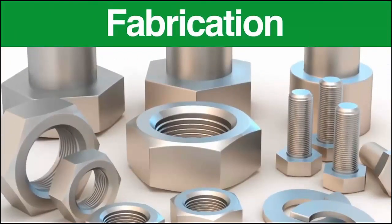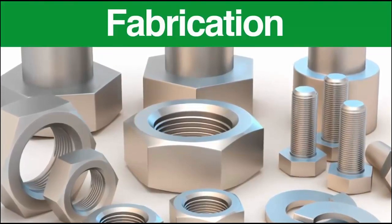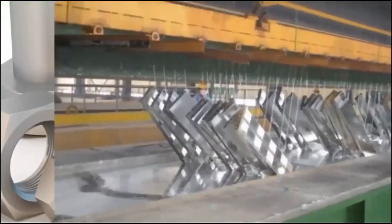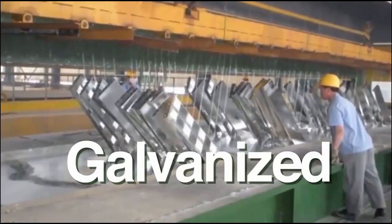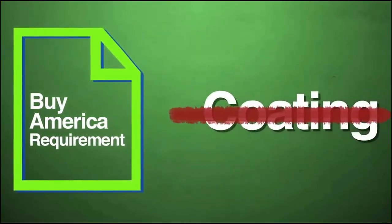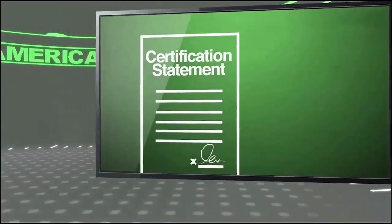Bolts, nuts, and washers used as connectors require separate certification statements since these are produced at different locations and use different manufacturing methods than the structural elements. The location of the final step, where a product was coated with paint or galvanized, must also conform to the Buy America provisions. However, Buy America material requirements do not apply to the coating material because it is neither steel nor iron. Verify certification statements at the time of material delivery to the project site.